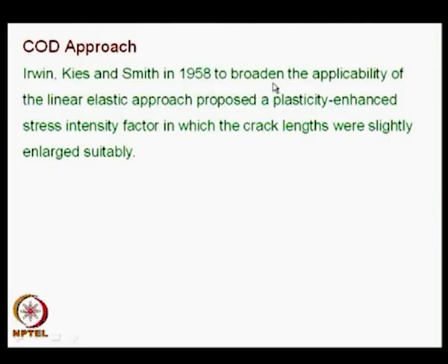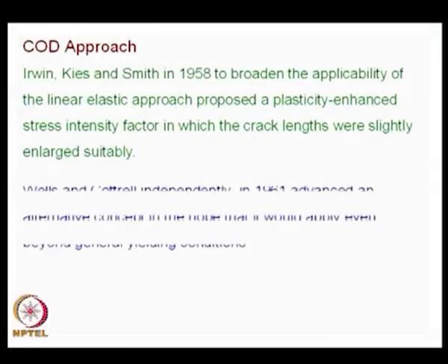When they wanted to broaden the applicability of the linear elastic approach, proposed a plasticity enhanced stress intensity factor, in which the crack lengths were slightly enlarged suitably. This we had seen. You had looked at Irwin's model, you had looked at Dugdale's model, you also evaluated what should be the incremental length that you have to add to the crack length and make that crack length as effective crack length. So, this was limited.